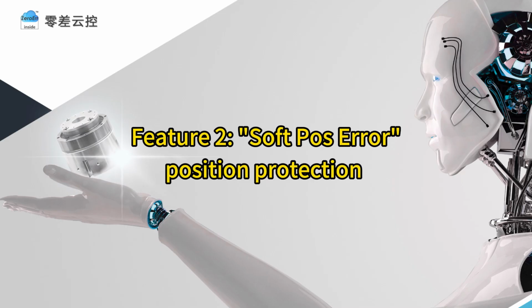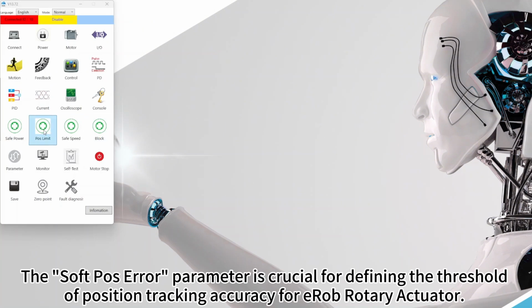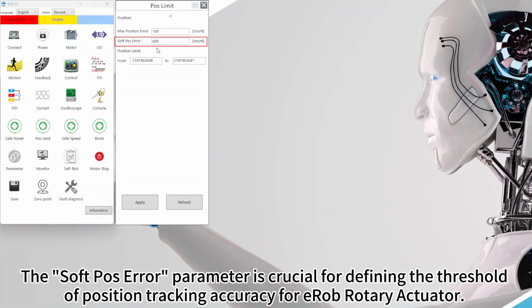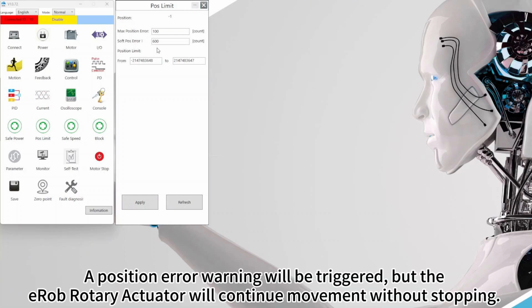Feature 2. Soft position error, position protection. The soft position error parameter is crucial for defining the threshold of position tracking accuracy for eRob Rotary Actuator. While utilizing this limit, when the actual position error exceeds the designated value, a position error warning will be triggered, but the eRob Rotary Actuator will continue movement without stopping.